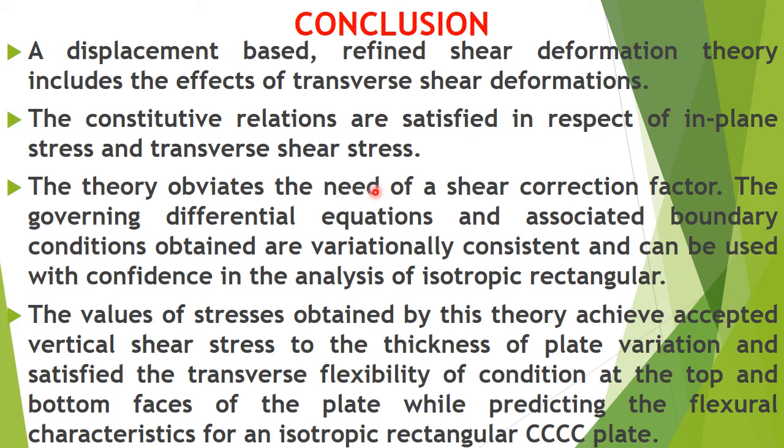So this theory obviates the need for a shear correction factor. The shear correction factor is actually associated with lower-order shear deformation theories like first-order and second-order shear deformation theory, by adding complication to take care of the effect of transverse shear stress.